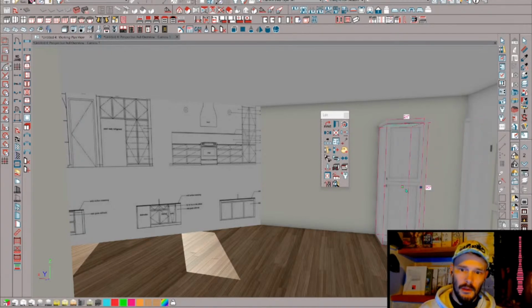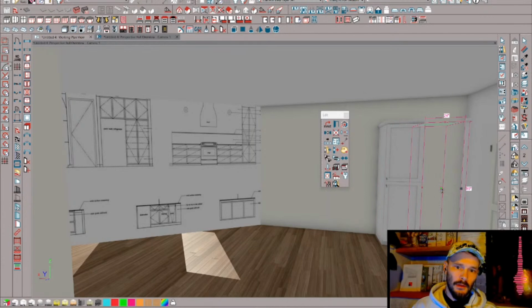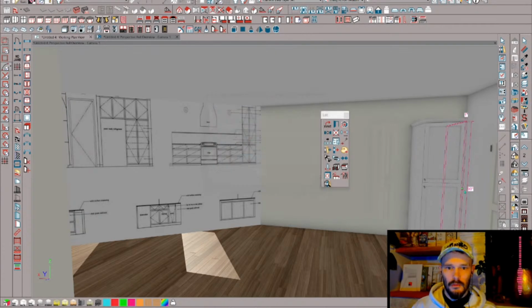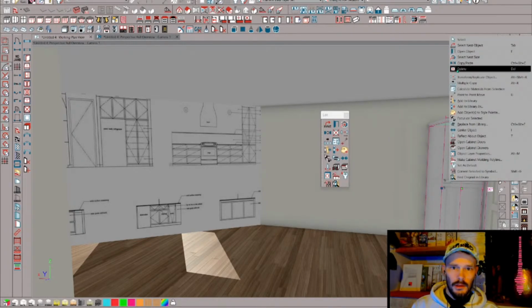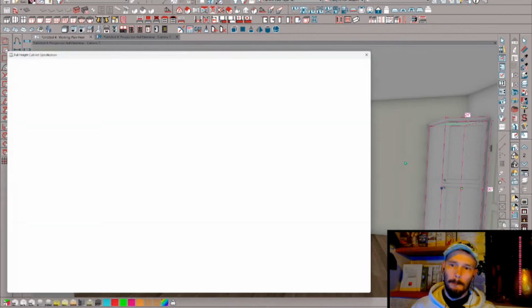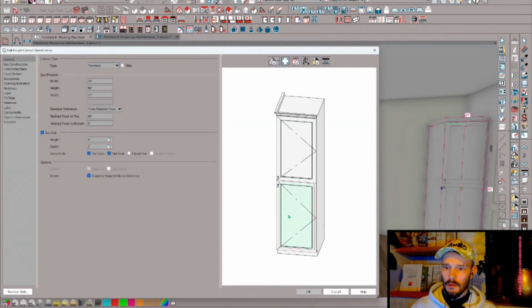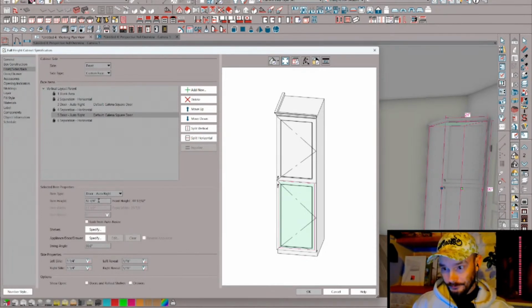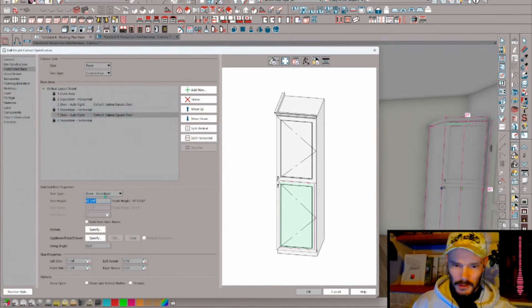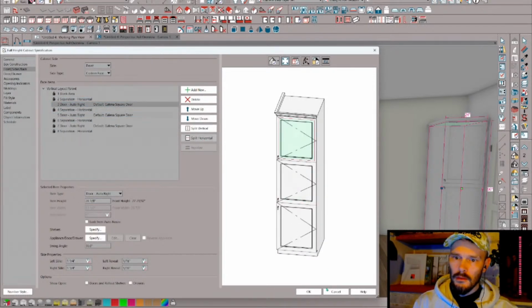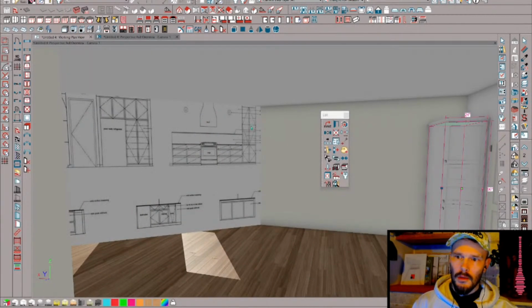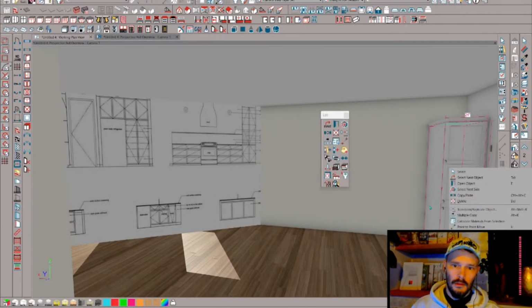So place that. Oh, let me make sure bumps are on. And then bump this to the filler. And now you can bump that filler to the wall. And this filler is 3 inches. I want it to be just 1 inch. We'll start with that. Modest. And then we can bump it to the wall. And let's open this. So it looks like we want this to be, oh, with overlays and everything, what does that make it? 8.5 or something? Something like that. Oh, and that's a full height door.